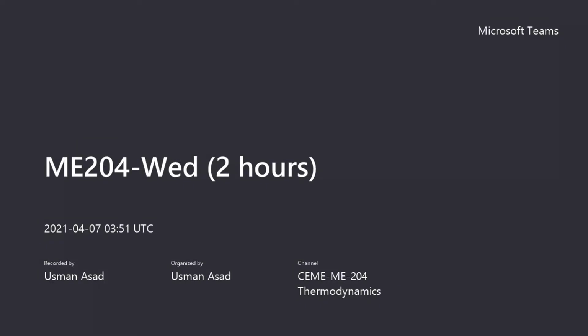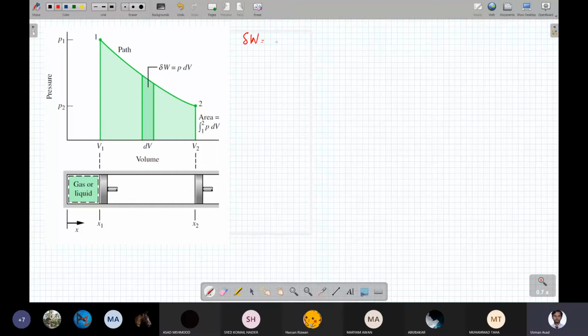Okay, so this is still recap, right? The incremental work done was force times dx, which can be written as PAdx or PdV. But for an entire process 1 to 2, the total work done is just going to be a sum of those incremental work dones, which is the integral of PdV for a process 1 to 2. Okay? So the next step really is to calculate the area under curves for different applications. The first case that we are going to discuss,